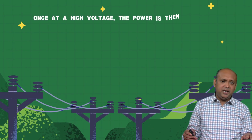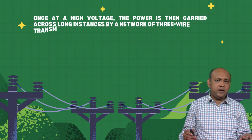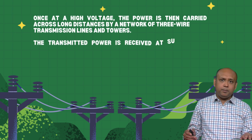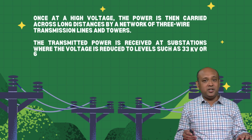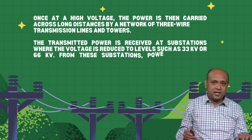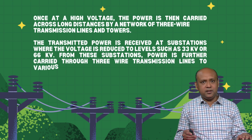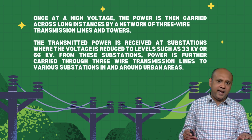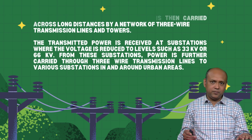Once at a high voltage, the power is then carried across long distances by a network of three-wire transmission lines and towers. The transmitted power is received at a substation where the voltage is reduced to levels such as 33 kV or 66 kV. From these substations, power is further carried through three-wire transmission lines to various substations in and around urban areas.